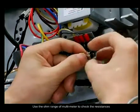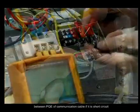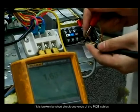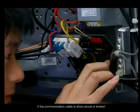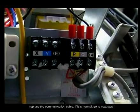Use the ohm range of the multimeter to check the resistance between P, Q, E of the communication cable to see if it is short circuit. Check if the communication cable is broken by short circuiting one end of the P, Q, E cable. If the communication cable is short circuit or broken, replace the communication cable. If it is normal, go to the next step.